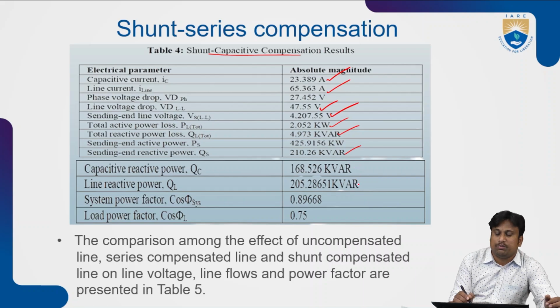So the capacitive reactive power requirement becomes 168 kVAr. Line reactance is also 205. System power factor is 0.89, which means it is almost reaching the 0.9 case. Load power factor is maintained at the same 0.7.